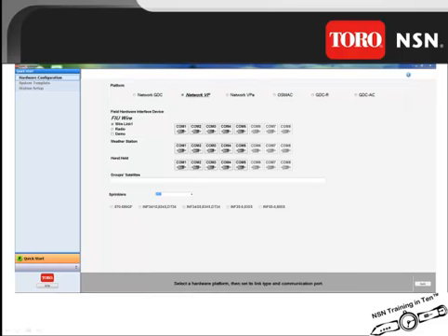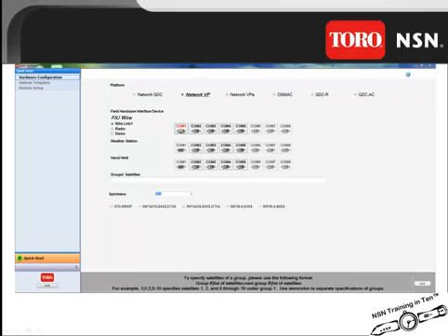You select the field interface hardware device selection, and that might be either radio or wireline depending upon your hardware type. You will then select which COM port to attach that to. Now this can be changed at a later date. We then select from the weather station what COM port we have attached the weather station to on the computer.